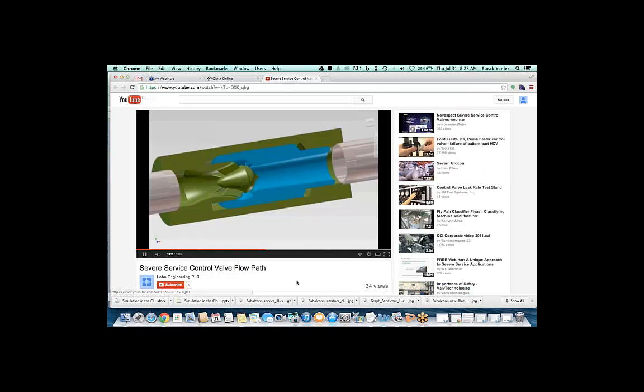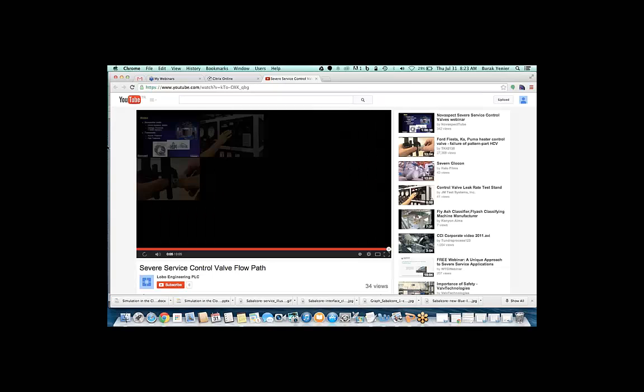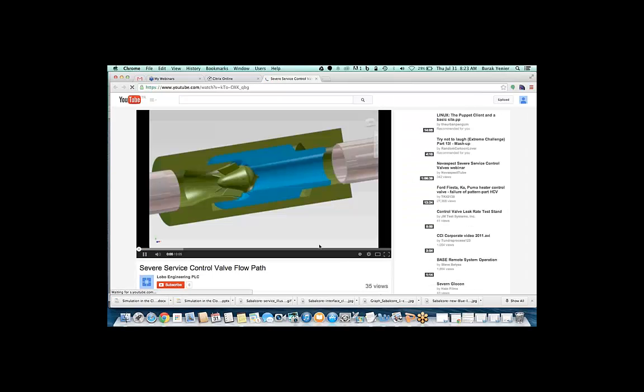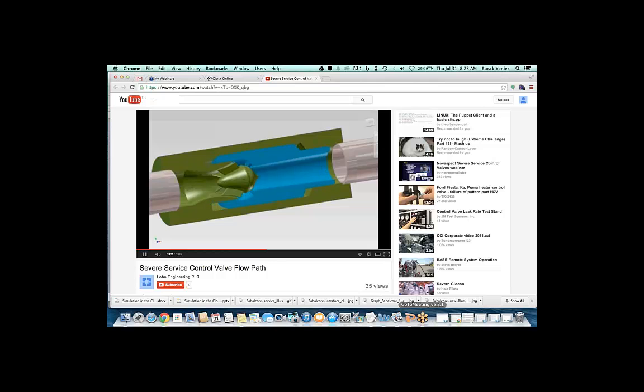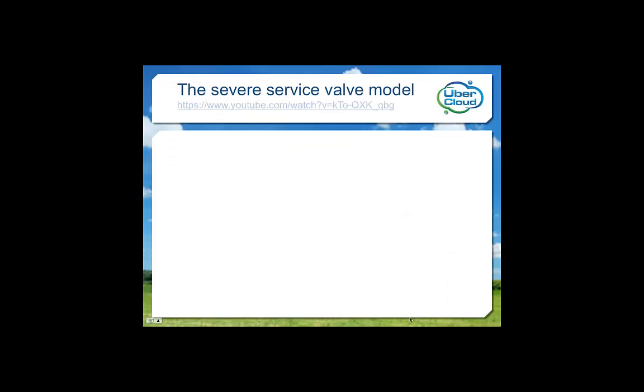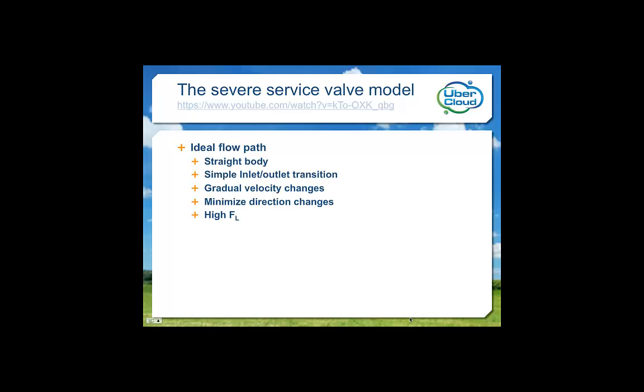The choice of actuator should allow flexibility. So the valve will need, as we get back to our slideshow, an internal rotary to linear drive that is efficient and does not compromise the flow path. So the optimized flow path is simple, with a sleeve that moves axially to change the annular area between the seat surface and the plug. Simple, sure, and later we'll figure out how to design a valve around it.